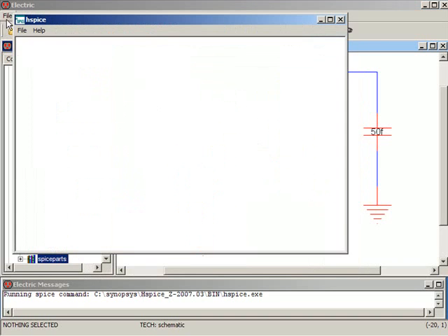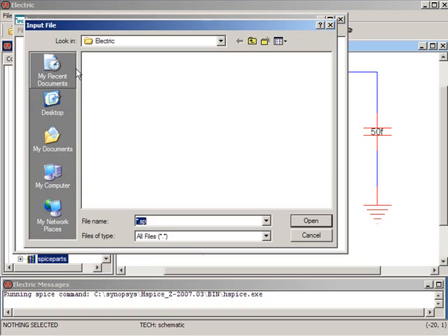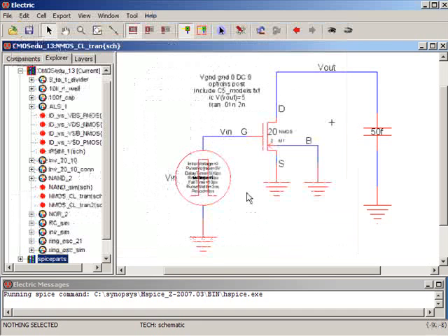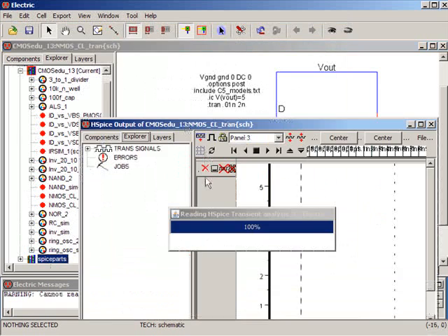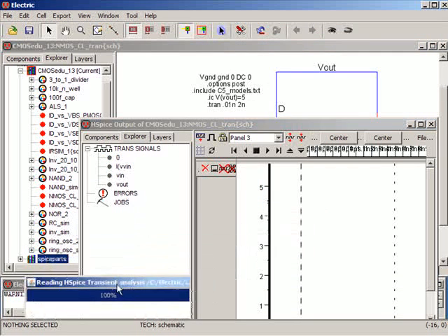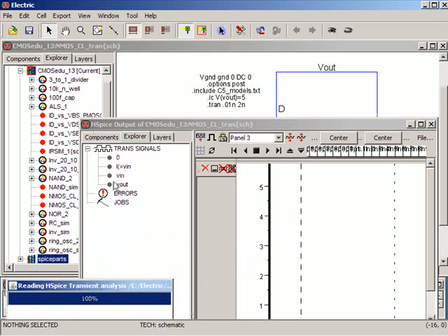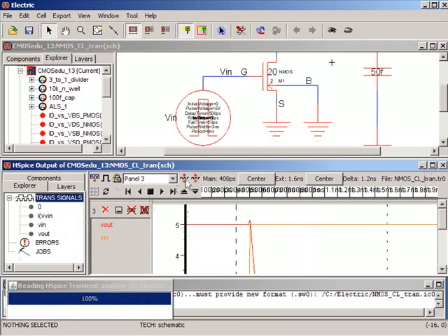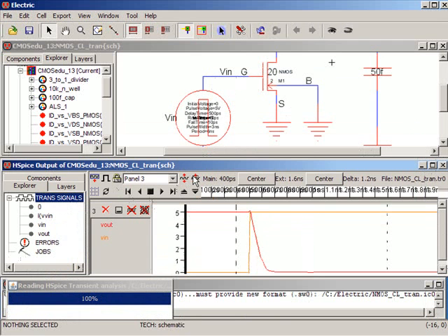Press S. Then we'll have to go to File, Simulate, and again, HSPICE wants to see SP files, so it looks for those, and we have to change this to SPI. Then we go over here, and it says Output File Save. Okay, now I'm going to hit Plot, and then let's go ahead and show this. Not sure why that's still there, but let's plot V out, V in, tile the waveforms, and reduce the size here.